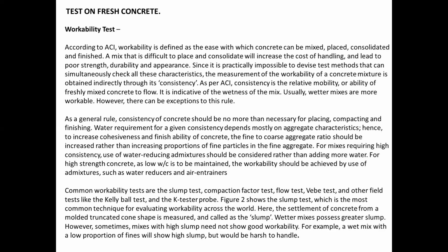Common workability tests are the slump test, compaction factor test, flow test, Vebe test, and other field tests like the Kelly ball test and the K-slump tester probe. Figure 2 shows the slump test, which is the most common technique for evaluating workability across the world. The settlement of concrete from a molded truncated cone shape is measured and called the slump.